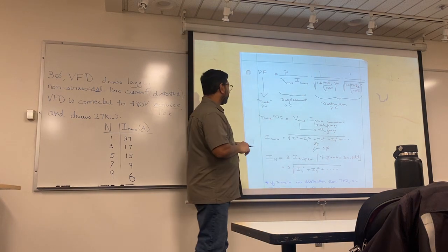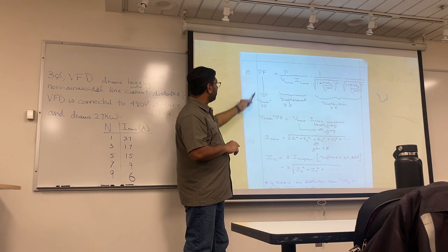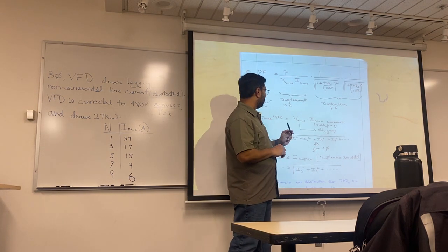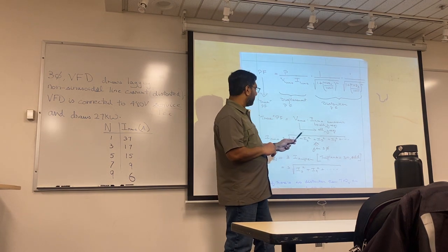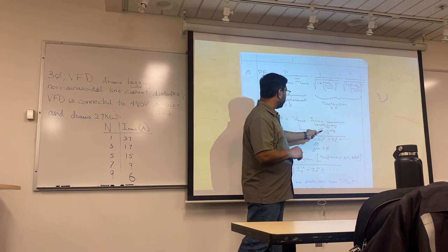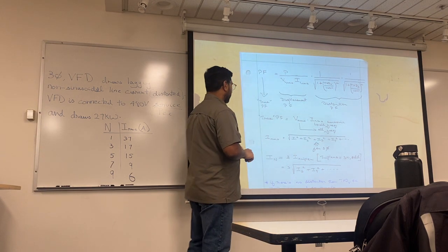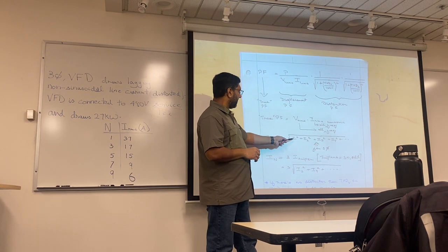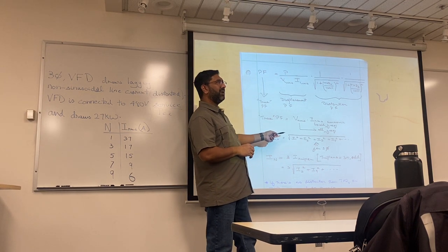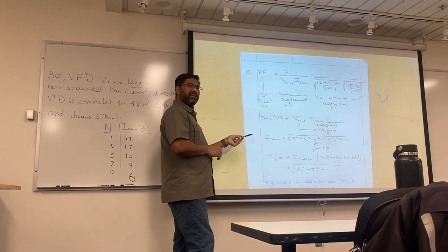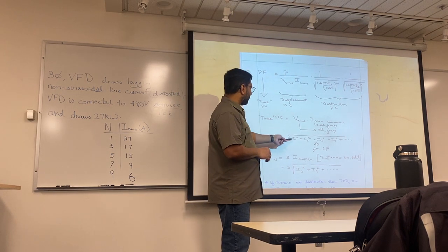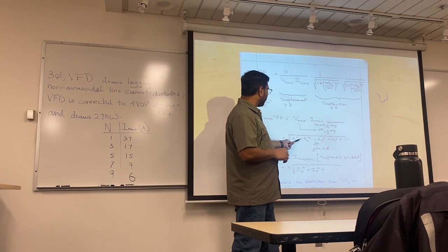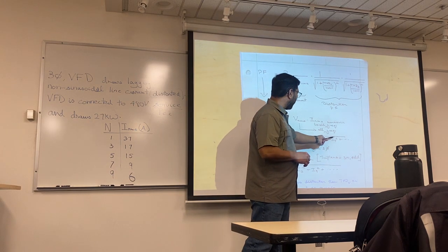So anyways, true power factor, this guy is VRMS, IRMS, of all the frequencies. And how do you find an IRMS? You take all the currents, and you have seen this formula when you were doing your, was it wire gauge? Then you took the currents. Oh, you were trying to find the IRMS, yeah. So I1 square, I3 square, I5 square, I7 square.